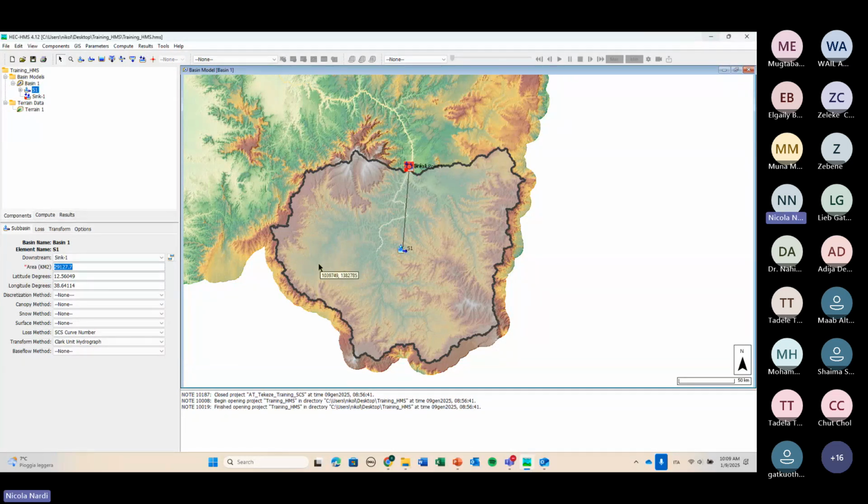We could have limestone or something like that. While here, in the valley, maybe our material is more alluvial. So we are talking about sand, silt, with a different infiltration. So we have a problem of both infiltration and land use. How to select a good curve number?